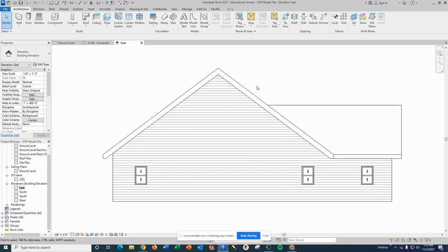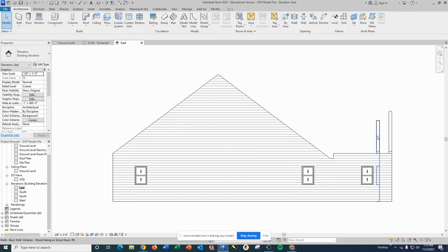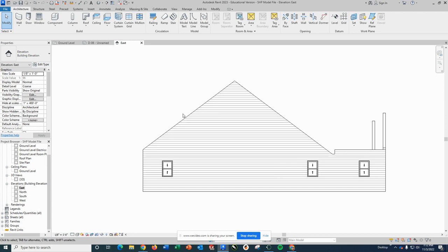And as you look at the elevation, we've already hidden a lot of stuff, but one of the big things we need to hide is the roof category. Okay. So truly, the easiest way to do it is probably just to hide the roof and to right click and hide anything else that is not a wall, a window, or a door. Literally, those are the only things you want showing. Okay. No furniture pieces, no nothing. All right. So again, this is going to become a three-dimensional model. I don't want my patio table engraved on my wall.